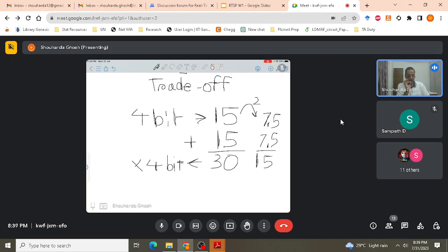Actually, since we are staying in a 4-bit number, what will happen is that this 0.5 we cannot save. So what is happening, you can understand, we are storing it in a 4-bit word, and we are representing it in integer format. So when you are scaling it down by a factor of 2, we will divide it by 2, but then we cannot represent 0.5 in our 4-bit integer. Yeah, is everybody understanding this point? Because it's very crucial for designing hardware. Please tell me if you are not able to understand this point, what is happening.